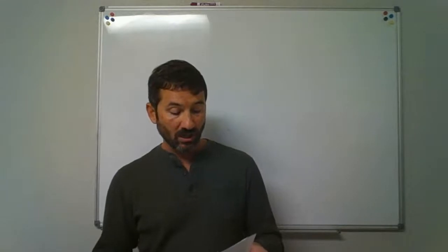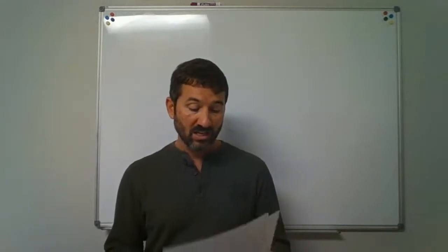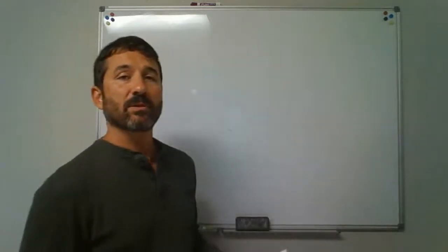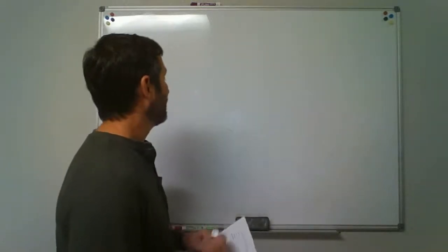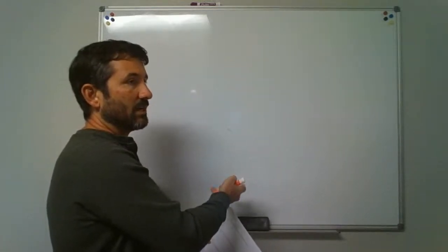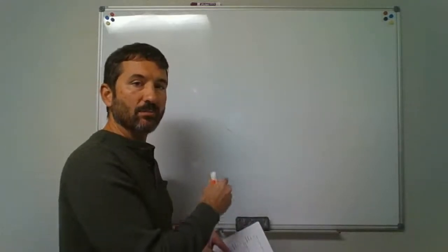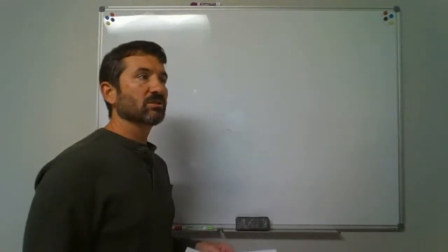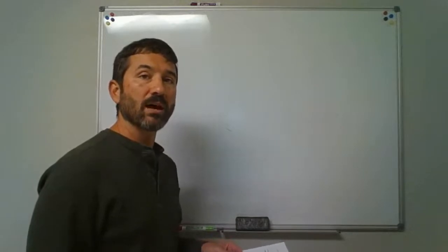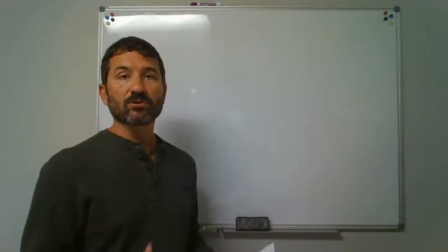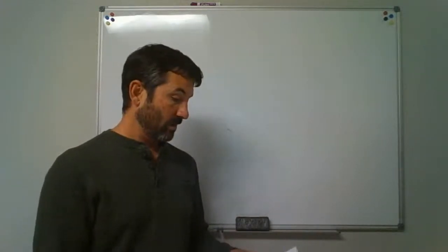And the last one, question 10. A trap seal primer is needed when a trap seal is subject to loss by evaporation. And we did mention that. Having that trap with a trap seal in a place where the water is going to be subject to evaporating out of the trap, under those circumstances you need to have a trap seal primer on that. Was that true or false? We've got to keep those trap seals primed.